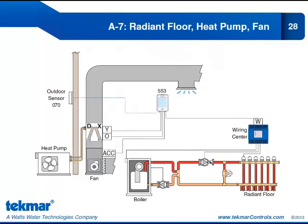Our last application, this time the accessory relay will be operating a fan instead of the dehumidifier or the electric strip backup. Our first stage of heat is still the radiant floor, so we have the W going to the wiring center. Second stage of heat from our heat pump with the Y relay. O for the reversing valve, and now my accessory relay will operate the fan.